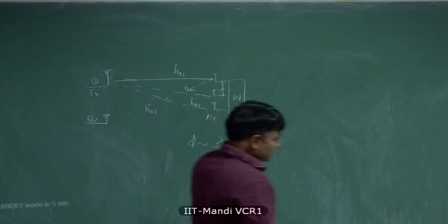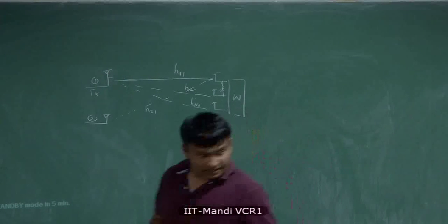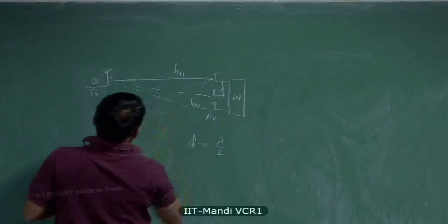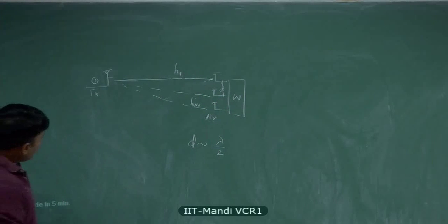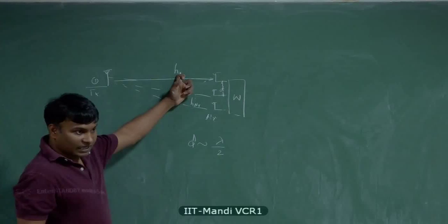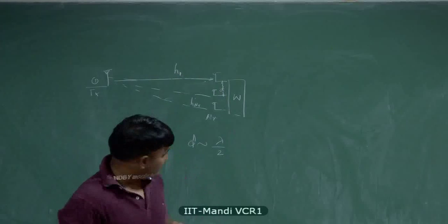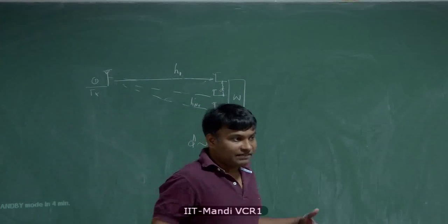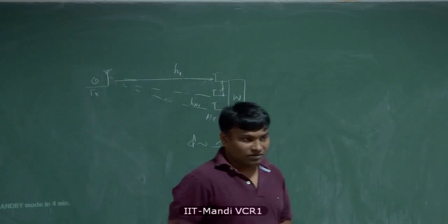So the question here is, why are we considering a setup like this? First, like I said, we will discuss a single transmitter, multiple antenna receiver, then we will generalize this. If it is a narrowband system, and if the channels have Rayleigh fading, having multiple receive antennas serves two purposes. Number one, it gives you what is called an array gain. What is an array gain? Having more receive antennas captures more energy. As a result, it produces a higher signal to noise ratio.